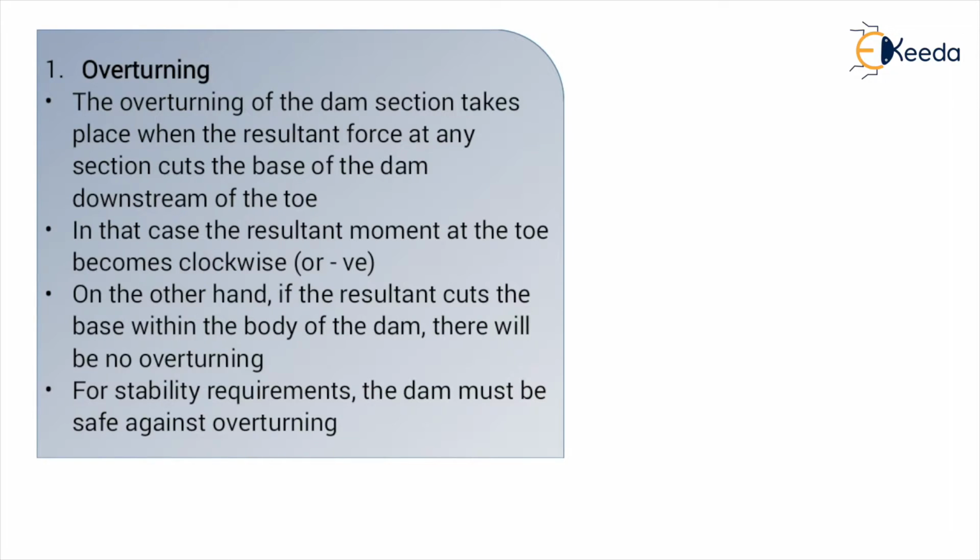See, what exactly is the resultant force? After calculating all the forces, we have to properly mention which are the horizontal forces and which are the vertical forces. After calculating the moments which develop because of these forces with respect to their CG, or with respect to their distance from the toe part, and after analyzing all this, we have to calculate the resultant force, the total force which is acting on the gravity dam.